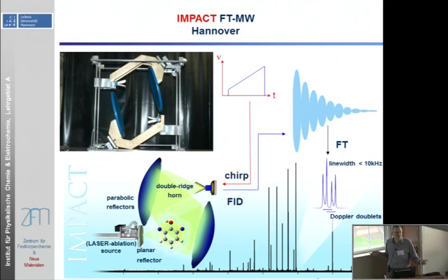Now it turned out that with a 1 watt amplifier, which we first thought might be enough, you still don't get a full polarization of a normal dipole species. You still need somewhat more, like a traveling wave amplifier. You can't avoid that, but you might do with 10 watts or 100 watts rather than several hundred watts. And the other thing is, even though this is not a resonator like the Fabry-Perot resonator, this is just basically a dual pass. You go through here, then it's reflected, goes back. It's not a resonator, so this doesn't limit your bandwidth by some Q.